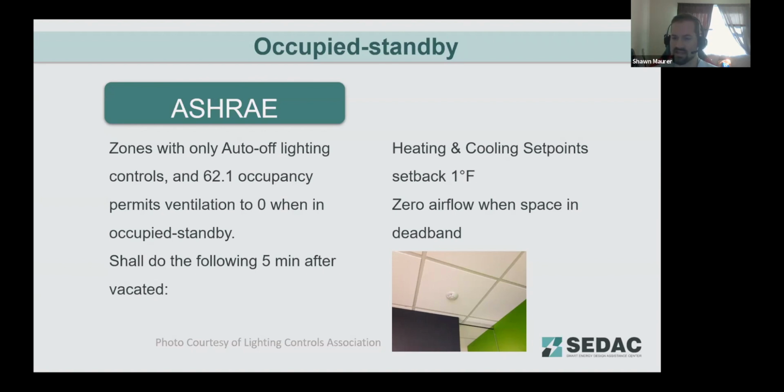As we noted earlier, the minimum deadband is 5 degrees. We've covered this in our IECC conversations, and it's also in the ASHRAE. So you've got that 5-degree deadband that prevents simultaneous heating and cooling. If you've got a 1 degree offset and then a 5-degree deadband, again, occupants aren't necessarily going to notice that 1 degree setback. The other thing they're trying to do here is make the setback something that can be recovered from quickly when an occupant walks back into that space. So again, it's not noticeable to the occupants, but can be quickly recovered, and is still going to provide energy savings by reducing airflow to an unoccupied space. You're backing off the VFD for that fan and saving that fan energy.